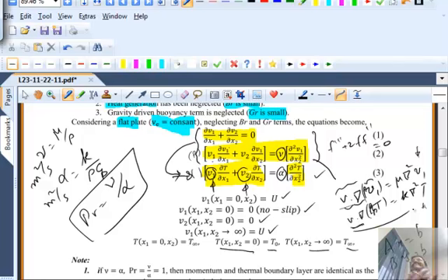So there is a one-to-one correspondence between the velocity profile that you will get for V1 and the temperature profile that you will get for T. Even though you are right in the sense that V1 also appears here, making it nonlinear, whereas here it is T, and that makes it linear. So one is a nonlinear equation, the other one is a linear equation, but the solution profile is governed by the same operators, the same rules. So the same profile. Another way of looking at it is, if you give me a profile for V1 and I plug it in this equation, that equation is satisfied.